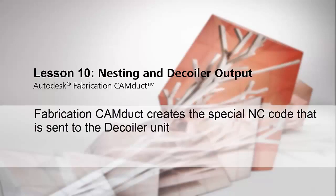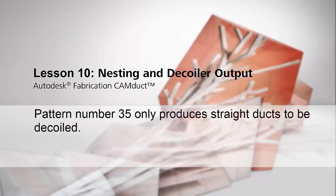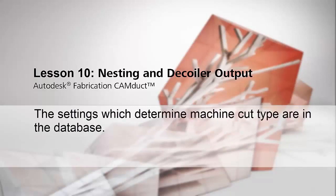Fabrication CAMduct creates the special NC code that is sent to the decoiler unit. The software knows which items to nest for cutting on tables and which to send to the decoiler unit based upon the pattern or item properties. Pattern number 35 only produces straight ducts to be decoiled. Pattern 866 can produce straight ducts that can be decoiled or sent to the table for cutting. The settings which determine machine cut type are in the database.